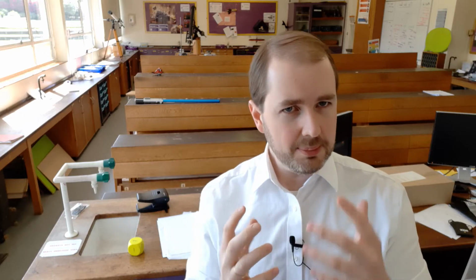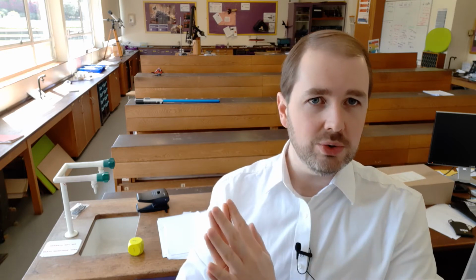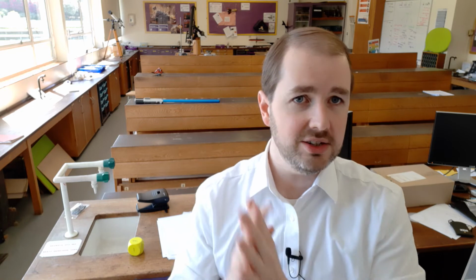Right, a couple of things I need to make sure you understand in that one. The voltage must be at its maximum at one end, and it should be 0 at the other end. So at the front part of our circuit, the positive part of our cell, you should have high voltage, and at the end you should have 0, as in all the energy should be used up by all the components in that circuit.